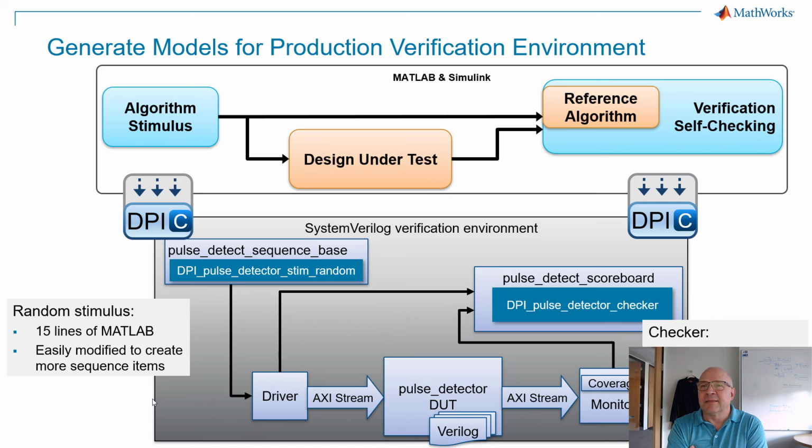So the other thing we've been seeing recently is more of our customers adopting UVM, the Universal Verification Methodology. Some are very far along, or a decade into that. Some are just doing it now. And we have an additional capability to not only just generate these SystemVerilog DPI components, but also to produce an entire UVM environment that can help bootstrap you if you're adopting UVM in your newer designs.